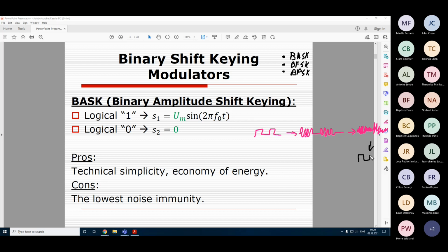So our purpose is to read what data is hidden in this noisy signal. And we are going to discuss the best way how to do that, the optimum receiver, optimum in a sense that it will make mistake, well, with lowest probability. So we'll start with amplitude shift keying, but all of them will be somewhat similar.